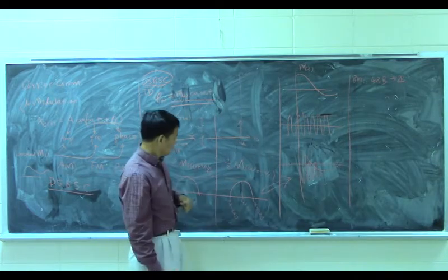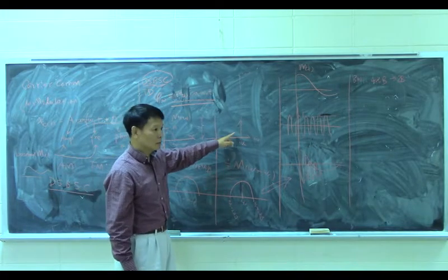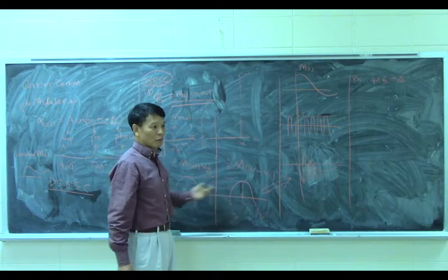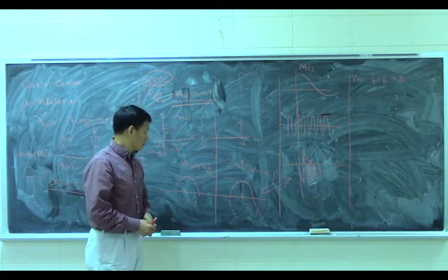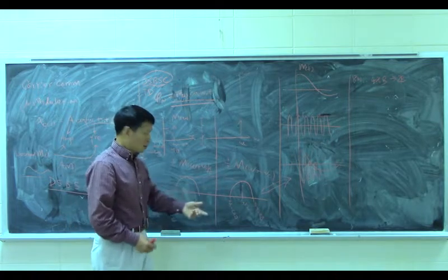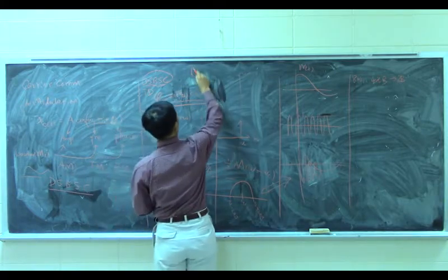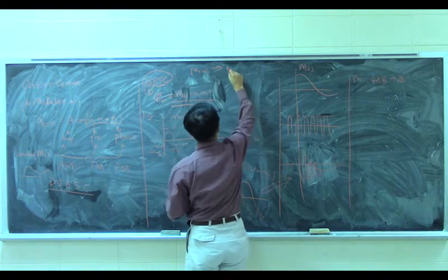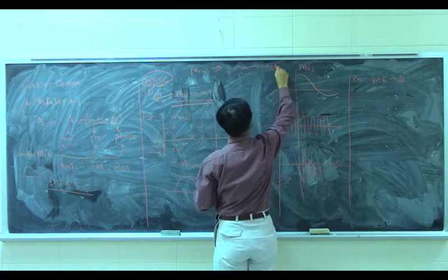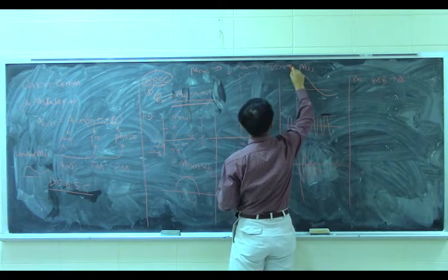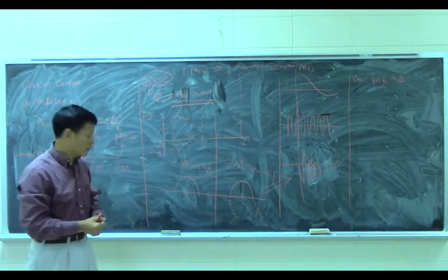Question? With the frequency, why is the amplitude half of the carrier signal? Yes, because we have two copies. So we add them up together. Good observation, right? Mathematically it will be half M(omega minus omega c), plus half M(omega plus omega c). So we have half here, and we have two copies.